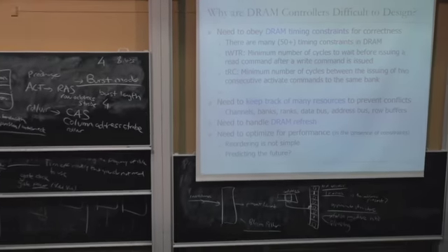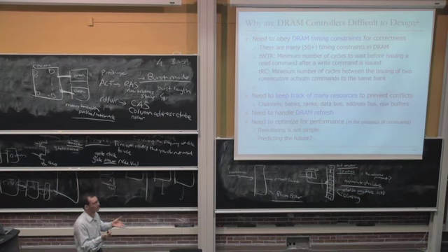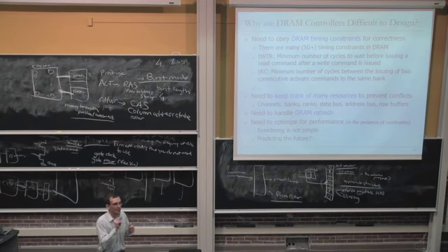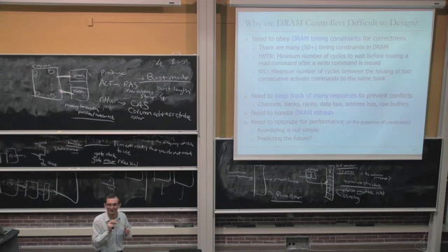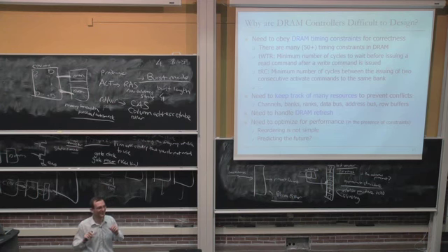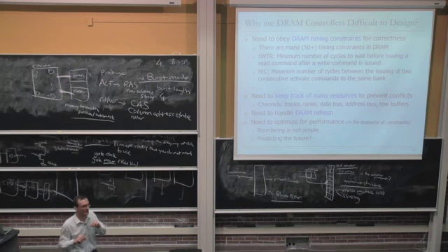So what logic do you need to reorder requests and determine which request hits in the row buffer? You have a request queue. Each queue entry has the row address it's accessing. And you have the address of the row that's currently open. What do you need to do? Sort of like a prioritized content addressable memory. Exactly, yes. A prioritized content addressable memory, right?